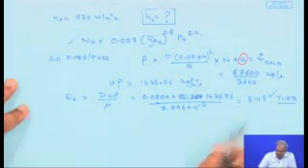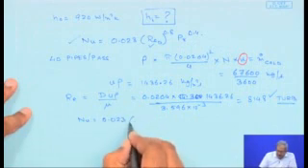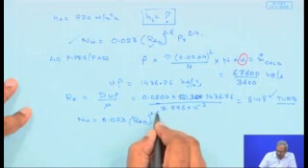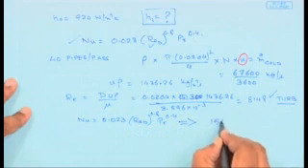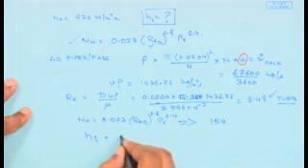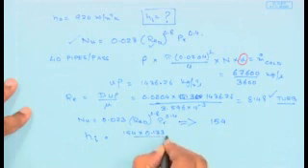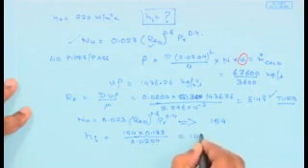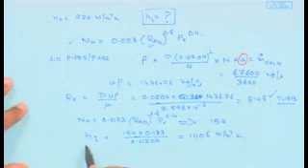So, with the value of Reynolds number and with the Nusselt number from the Dittus-Boelter equation, this would give you the value of Nusselt number equal to 154, and this would give you the value of the heat transfer coefficient on the inside equal to 154 into the value of k by the value of D, 1006 watt per meter square Kelvin. So, this is another important result, that I know what is the value of my hi.